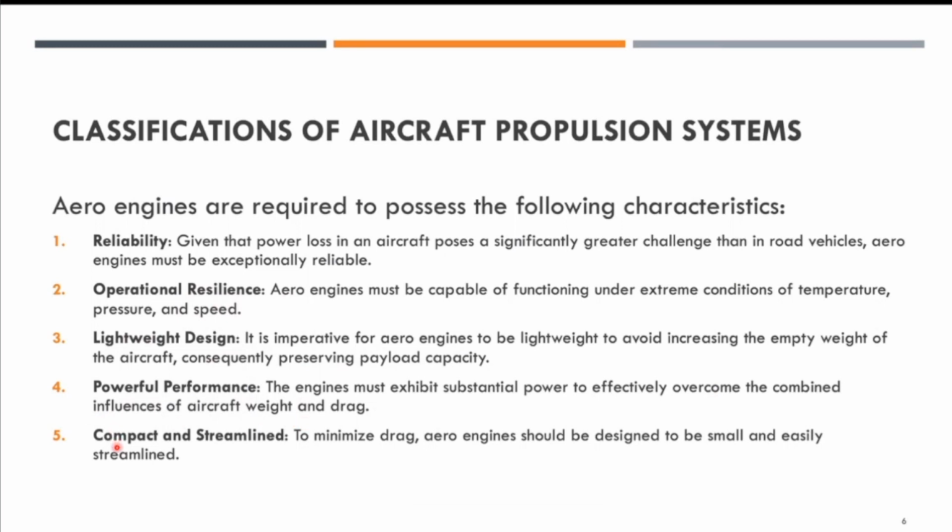And the fifth characteristic is compact and streamlined. You do not want to have an engine which is very bulky. It will of course increase the drag. So you want to minimize drag. You want aero engine to be designed as small as possible and easily streamlined.